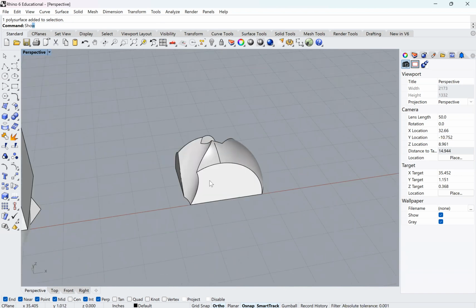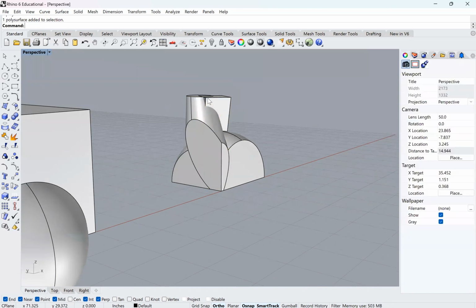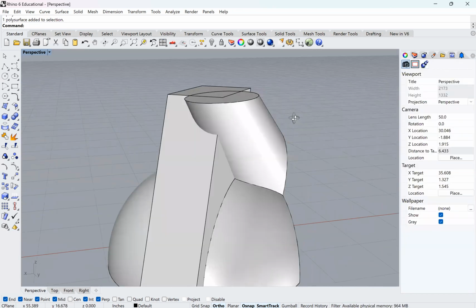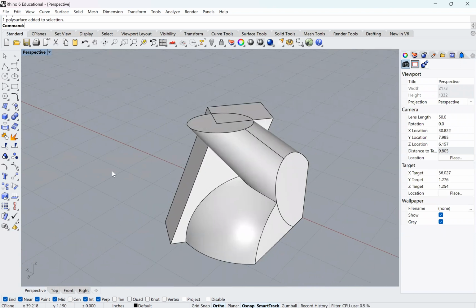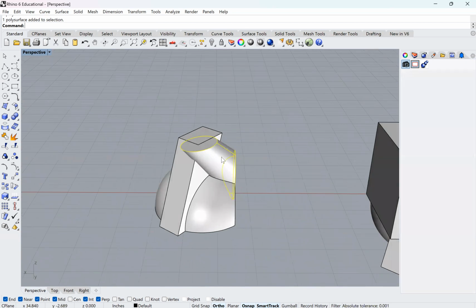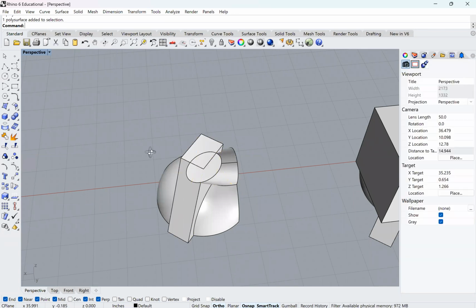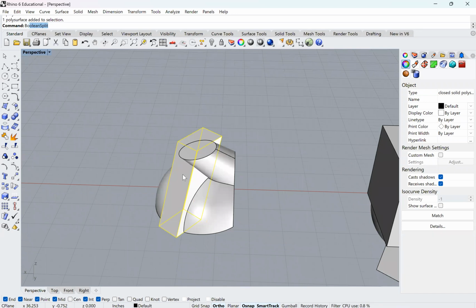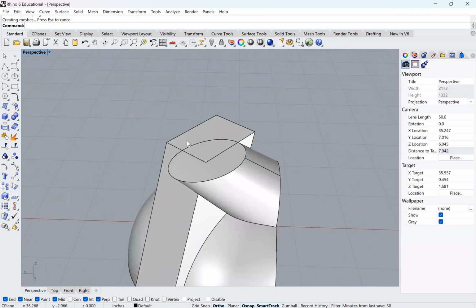This is one of our 3D printed pieces. Right? And now we have these 2. And these 2, now we have to decide which one slots from the other. And I think the most logical thing is to say, I'll carve this one. I'll keep this one solid and I'll carve that little corner out of my box. So again, now I would grab the box and I'm going to do a Boolean split. Subtract that piece from it.